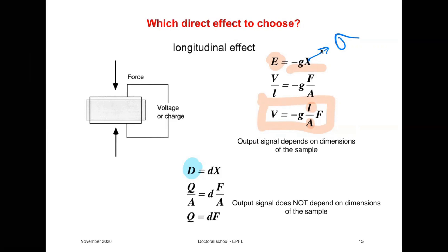When you look at a D coefficient, longitudinal, this is valid only for a longitudinal response. The applied force and the resulting charge for a given force doesn't depend at all on the dimensions. You can take a long or a flat sample or a cubical sample. You will always get for a given force the same charge, and that simplifies things a lot.